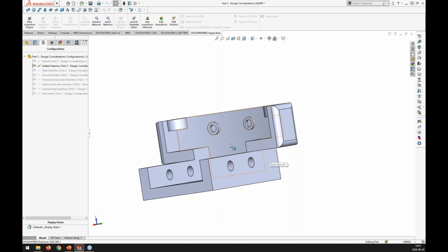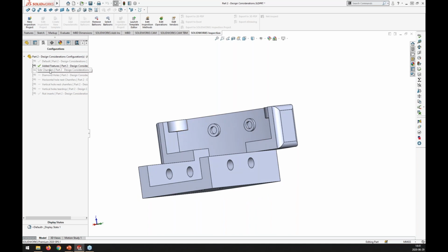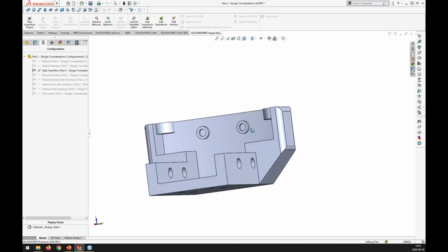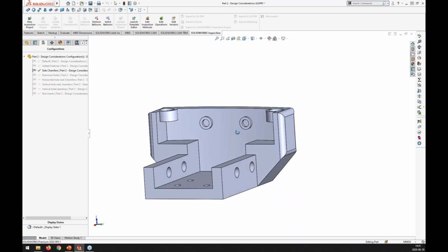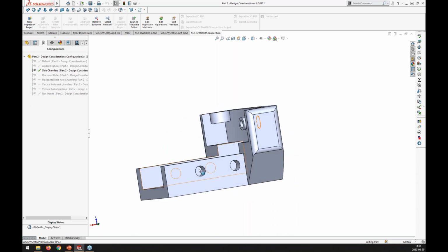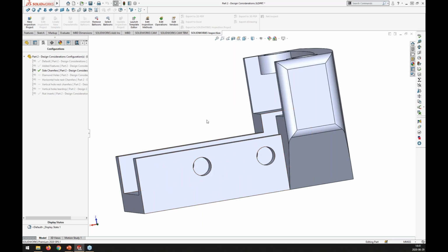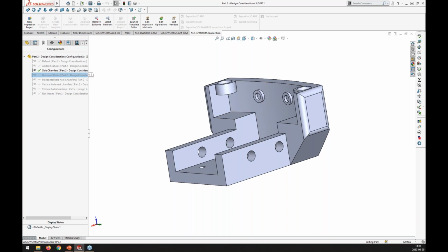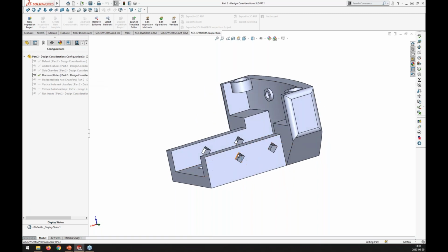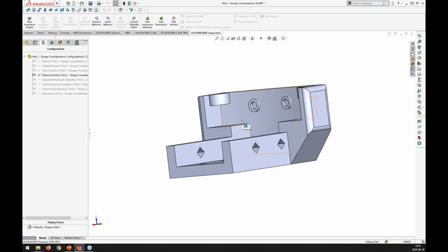As you remember from the first short slide, chamfers can make your design self-supporting very easily. So what we can do is just put a couple of chamfers here and there, and it would be self-supported. Next, what we can look into, you remember the holes. These holes would require some support structures printed in between. Let's say that we have an opportunity to drill them later and we can modify it. So what we do is change those holes to diamond shape, undersize them a little bit, and we say that we will drill them afterwards.